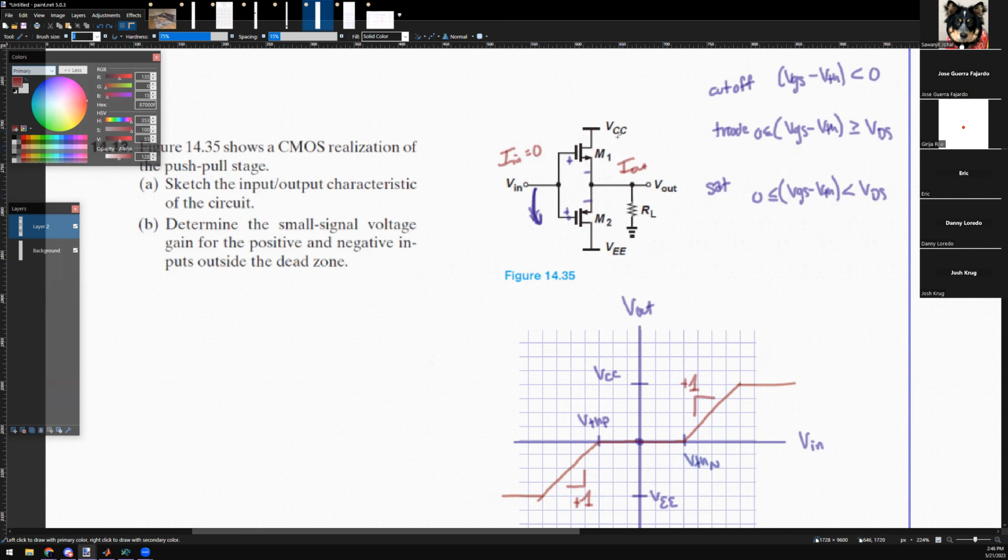This is the last stage that goes into your audio amplifiers. This is what drives your speakers. When you drive like 1,000-watt speakers, you have to have such a stage to actually push real current through your speaker load. By that you mean you have to have a PMOS and an NMOS, or just in general? Typically, you have a push-pull. Yeah, you have a source follower. You have a push-pull stage.